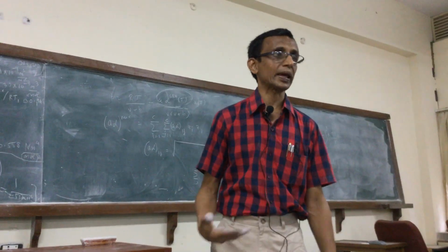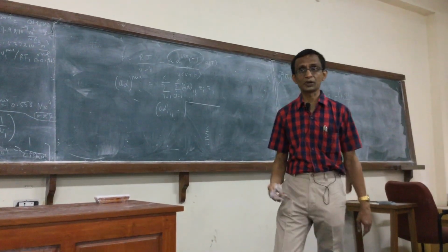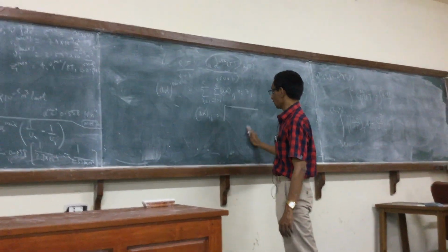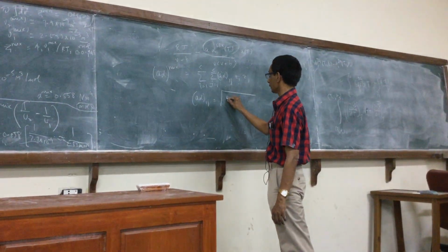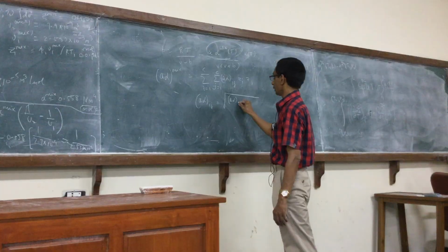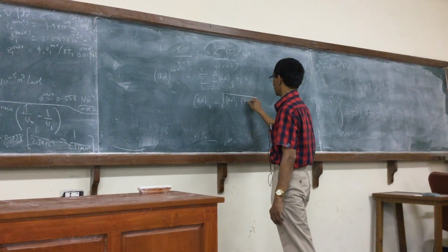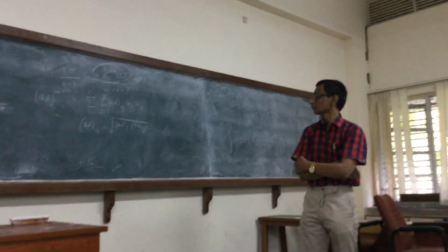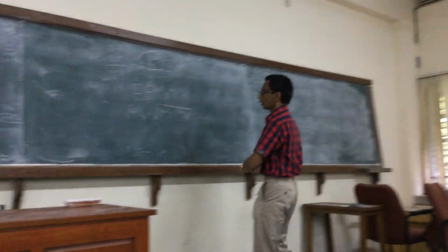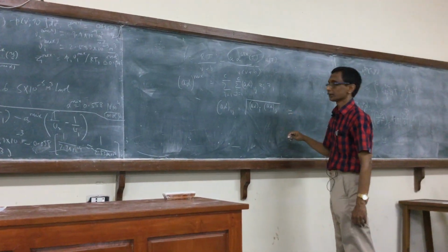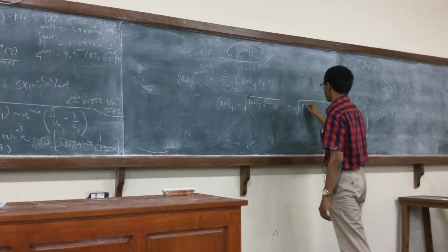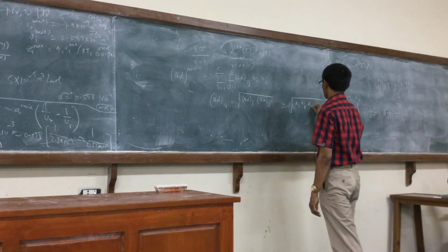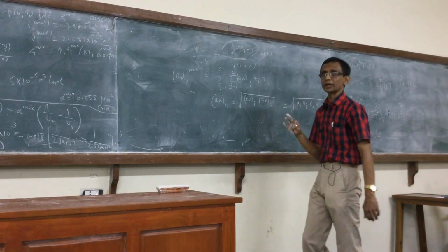They introduce something called the Kij, which could sometimes be a function of temperature as well. Right? So now A alpha ij, I'm going to call this the square root of A alpha i times A alpha j. So now I can split it, and this will be the square root of Aij times alpha i alpha j. So both have to be taken into account.